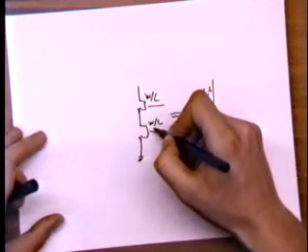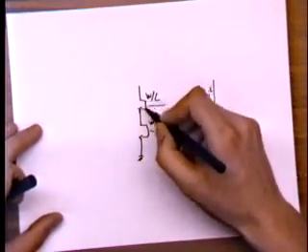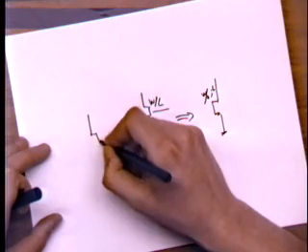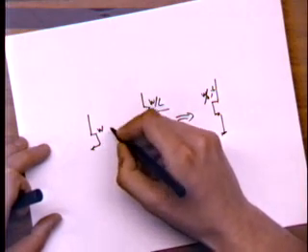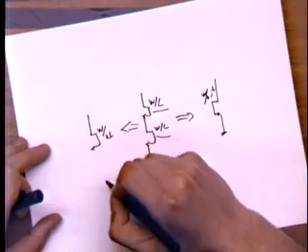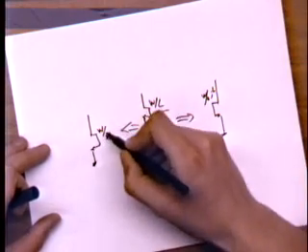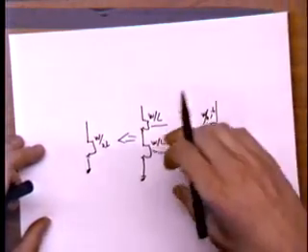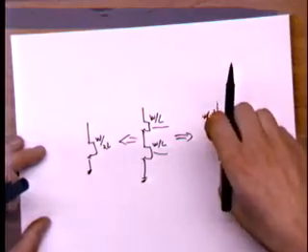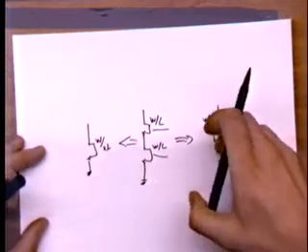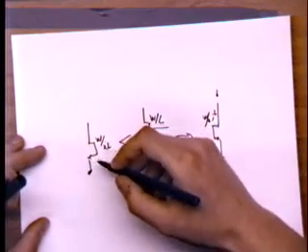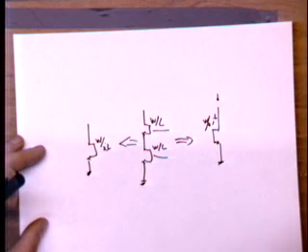Whereas physically, what happens is that the channels of these transistors are in series, really. And so this looks more like a single device, which has a width of W still, but a length of 2L. So here's the subtlety, right? We are realizing a W over L ratio that is half of the original one in either case, okay? So therefore, if these transistors were quadratic, a transistor which has W over 2 over L or W over 2L will give you the same exact IV characteristics, right? And therefore the same delay.